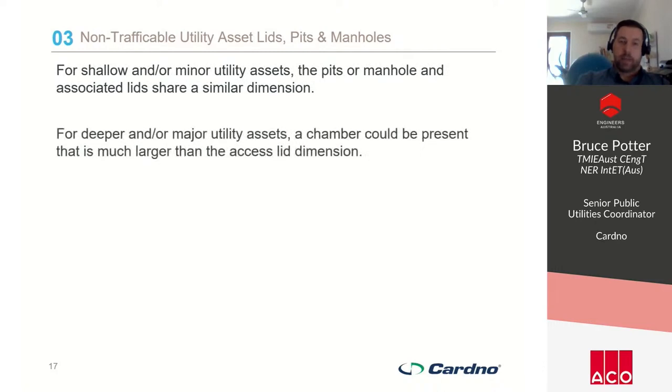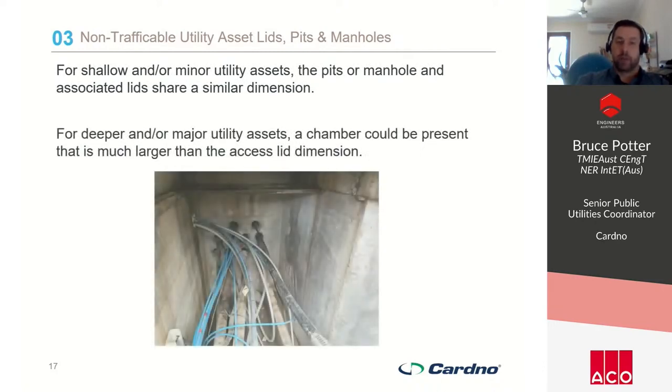For minor assets, pits and manholes generally have a similar dimension. As you walk down a residential street, most of the time the Telstra and Energex pits are a stock standard size, and the pit below it is generally around the same size. But there are occasional exceptions where a deeper or major utility chamber, which is basically a big concrete structure below the ground, below the lid itself, could be present and is much larger than the lid itself. This can cause a lot of coordination issues in a lot of the designs that we have.